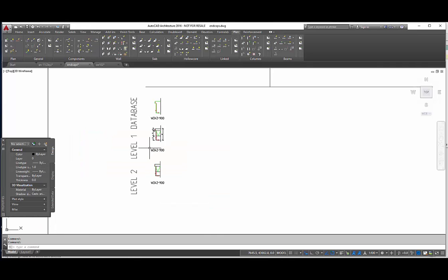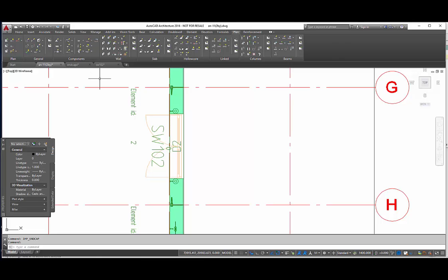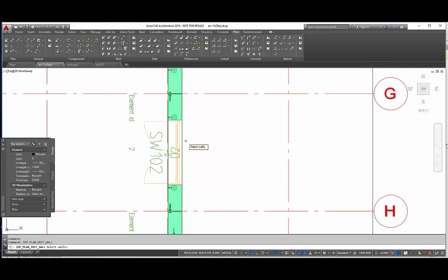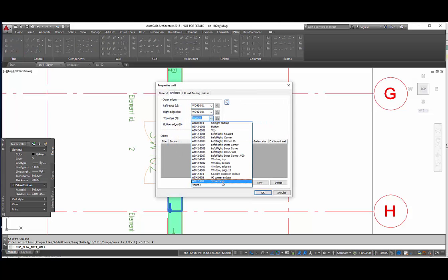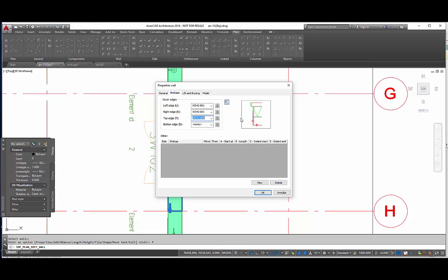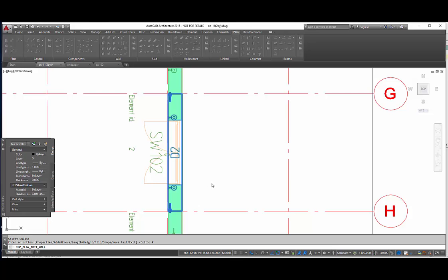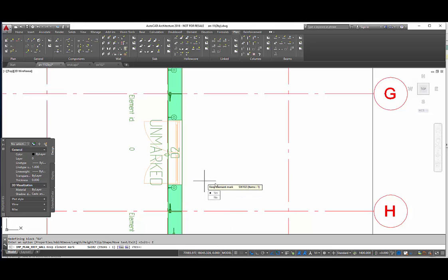To start with, we have to insert one more end cap for a sandwich wall top edge. To do so, I go to Wall Properties and click on end caps. In a top edge you have to choose the latest end cap you have made and confirm. Now it will ask you if you want to update lifts and bracing and keep the same element mark.